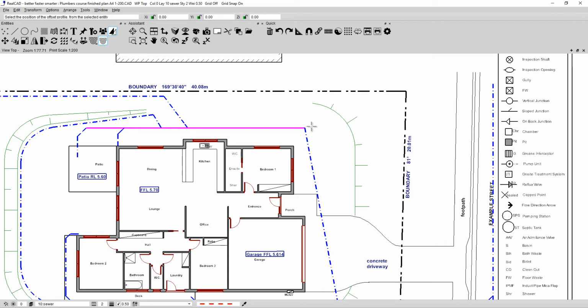One of these lines will be highlighted, and it's this one, and it just wants to know where, relative to this one, do I want this second line to go? Well, I actually want it to go probably about here. So you can see that I've now got a duplicate of this line and this one, offset by where I clicked, and they are direct copies, but they're done in the current line style because that's how we're drawing. I'm going to right click out of there, right click one more time, and it takes us back to where we were.